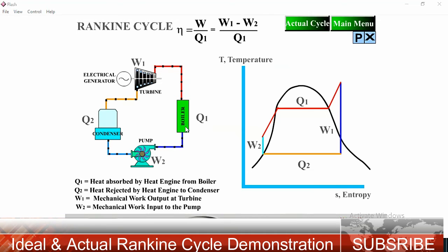Here is the energy equation for the steam turbine for unit mass flow rate. Suppose that m is equal to 1, so Q is 0 for an isentropic process, you can say a reversible adiabatic process. So Q is 0 since the process is reversible adiabatic, if we neglect the change in potential energy and kinetic energy.